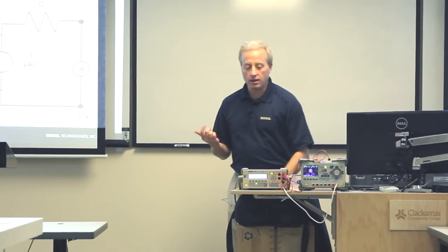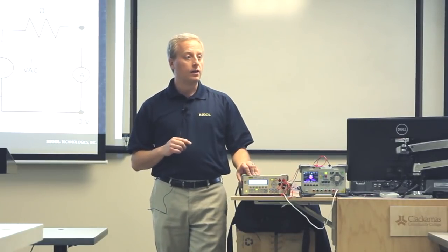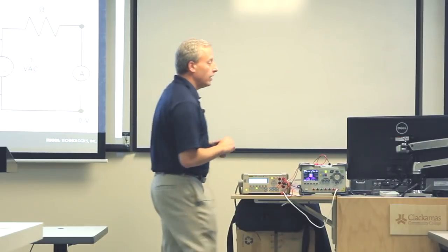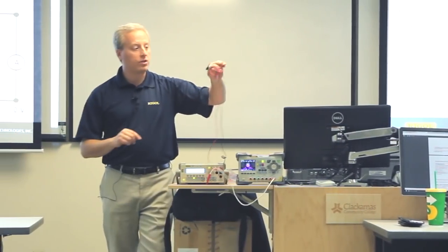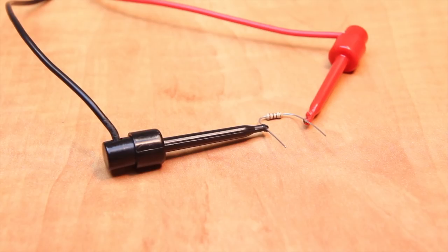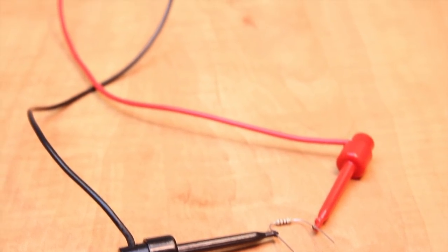Another interesting capability is the 4-wire resistance measurement, which is why you have the 2 sets of plugs in the front of the DMM. You can separate the wires for sourcing the current and measuring the voltage. What that allows you to do is really isolate the resistance. Even in this configuration, we're taking a measurement of the resistor, but we're also seeing the resistance of the wires, because it's just pushing current out these 2 plugs and looking for the voltage developed across them.